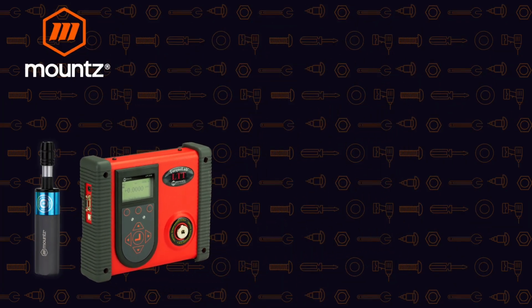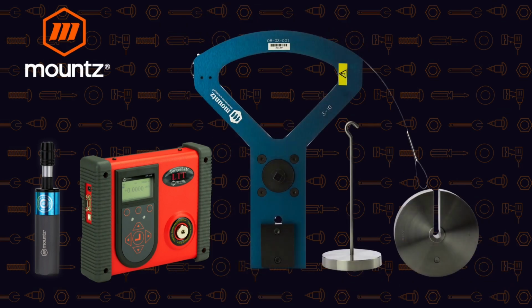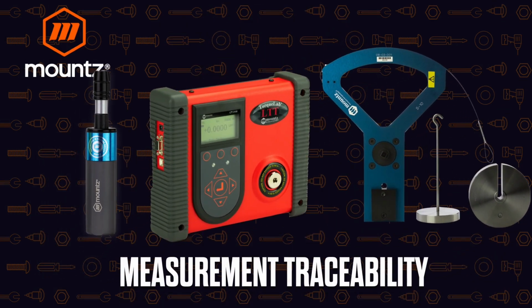And so in this case, there is a function which we call traceability. The wheels and the arms and the weights that are used have to be calibrated to a certain standard. Those weights then are used on the torque analyzer, which has its own ISO specification and ratios. And then we have our tools, which have their own standard as well. So if we use a tool on a calibrated torque analyzer, that is now traceable back to the wheels and weights and so forth.